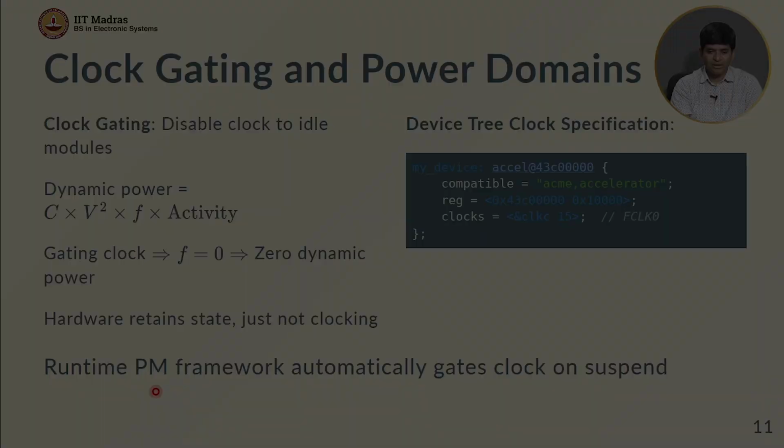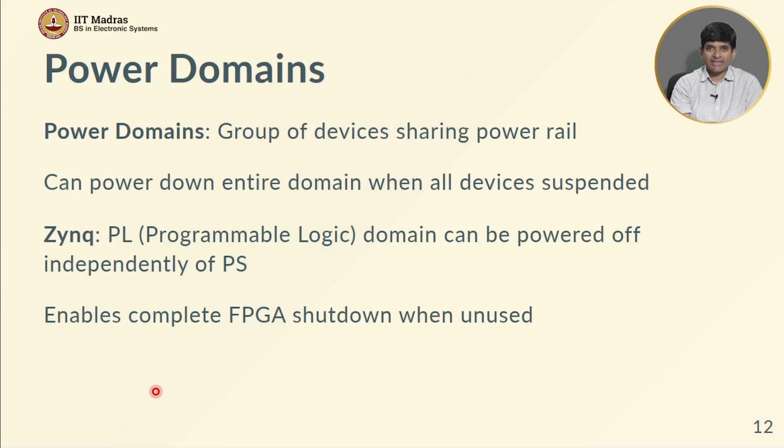Okay. Now a power domain is something related but also slightly different. It means that what you have is a group of devices sharing a power rail. The term power rail basically means, the reason why they are called power rails is because you usually have parallel lines VDD and ground, in between which you have the standard cells, right. So those are called the rails between which the cells are arranged.